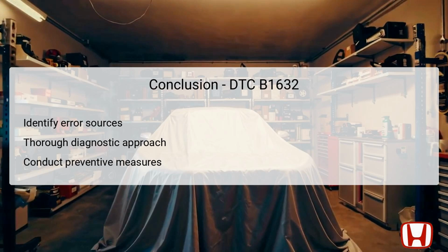This methodical troubleshooting not only resolves the immediate issue, but also lays the foundation for effective preventive maintenance practices. By being proactive in wiring inspections, connector checks, and software updates, you can mitigate potential future problems associated with DTC B1632, ensuring long-term vehicle reliability and performance.